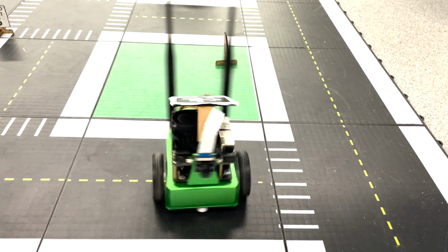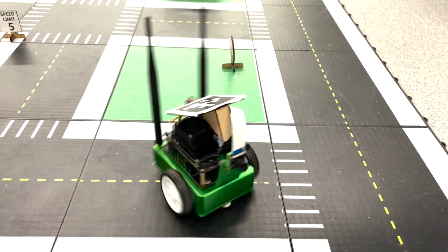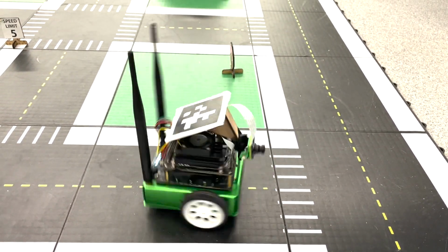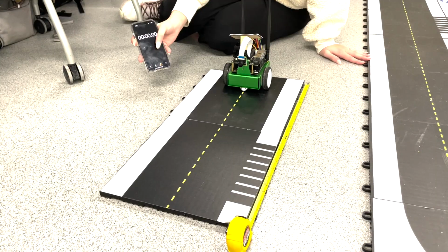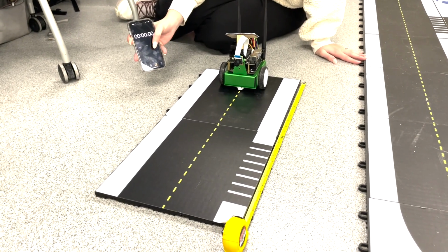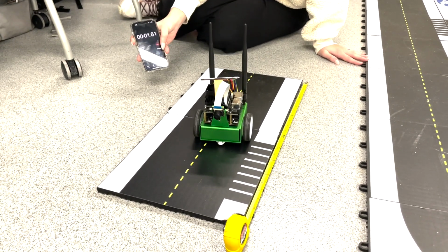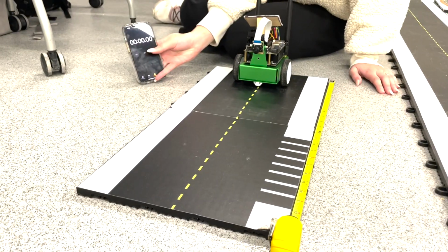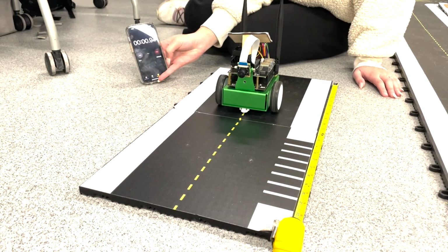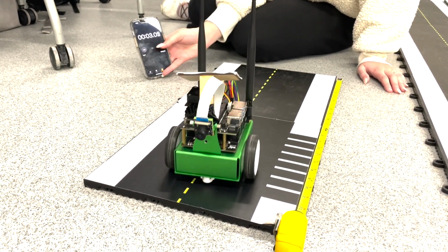Here are some examples of the left and right motors moving at various speeds. Now that we gained an understanding of the main functions of the JetBot, we needed to calibrate the wheel speed. This was done by doing multiple iterations of setting the JetBot down a straight driveway that was 2 blocks long. We timed this and recorded the distance from the center line for each run to eventually calculate the bias.